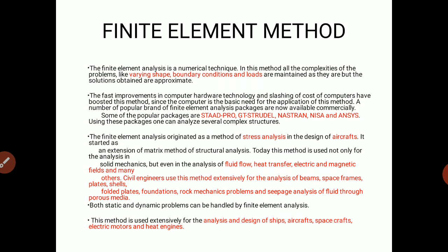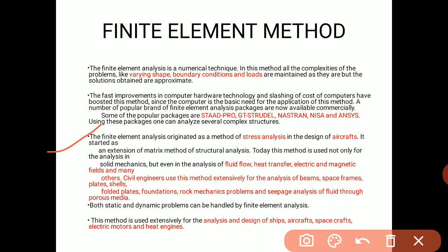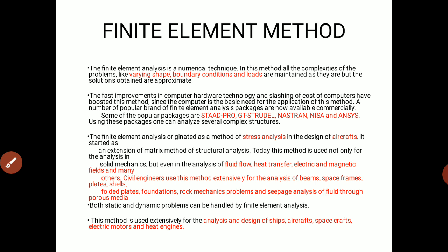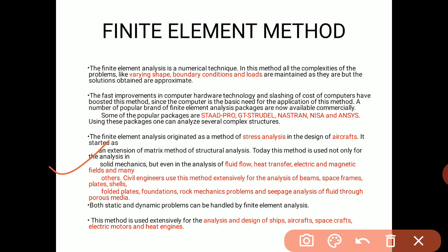Finite element analysis originated as a method of stress analysis, so we are going to analyze the stresses basically. In the design of aircraft, it started as an extension of the matrix method of structural analysis. Since we have used the flexibility matrix and stiffness matrix methods, we know how to form the matrix, what the contents of that matrix are, and the idea behind the stiffness and flexibility matrices. We know this much, so one can easily form a finite element matrix.